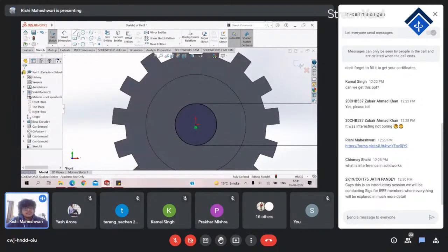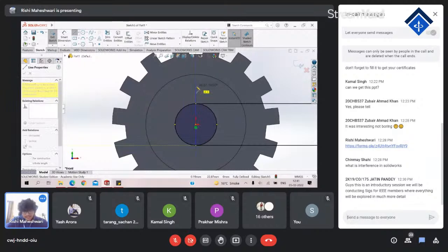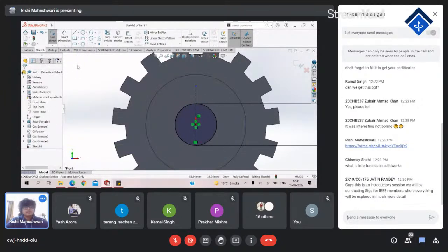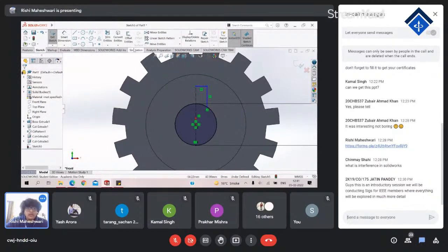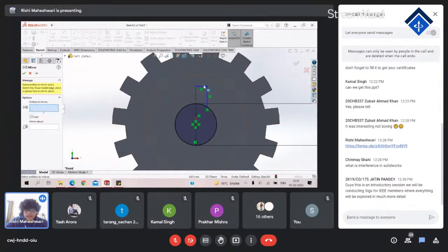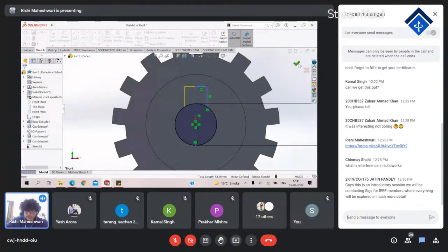So first things first, what I told you, center line is always the reference point, but herein I would extend it a little bit, and let's select OK. Now let's go to line. Let's go here. First of all, I'm just selecting the outline. I'm not going for any dimensions right now. First, we'll do the mirror entity, since the smart dimensions would also be replicated. So let's mirror it about the center line here. Let's click OK. The preview is already made.